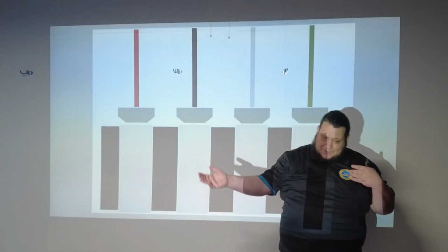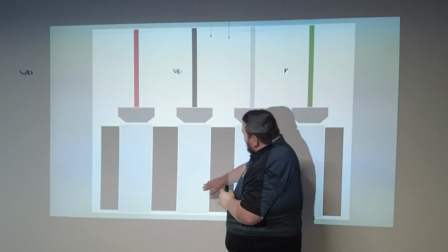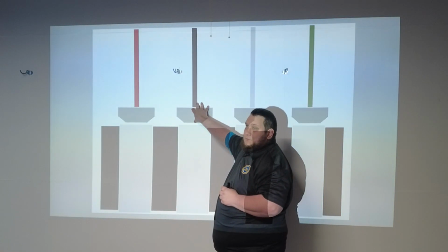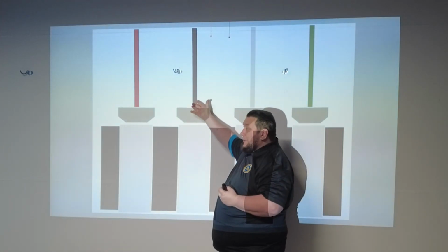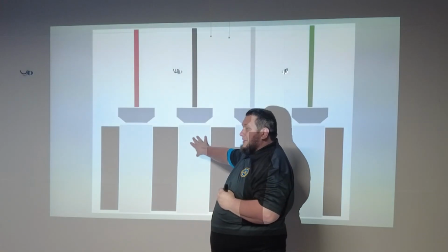So, customer takes off, they go to their next campsite, they plug in, they reel out their shore cord out to here, they plug it in. They don't have leg 2. That's one way that we can lose a leg, is if they extend or retract this reel while it is powered.